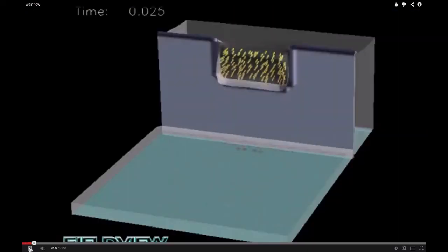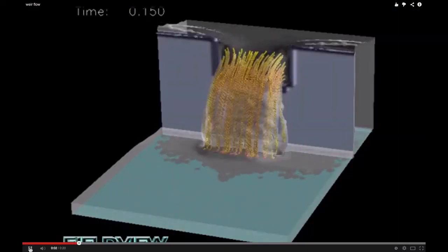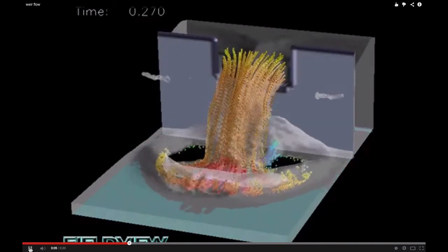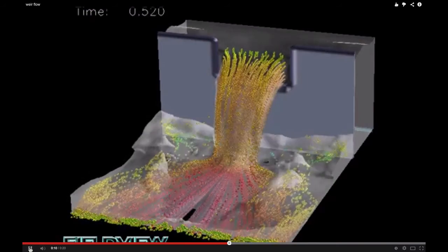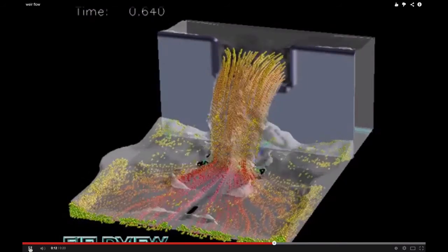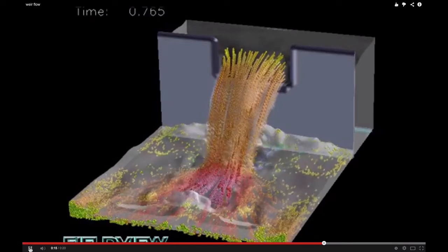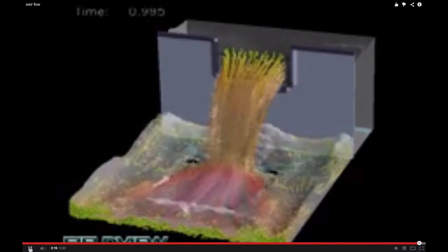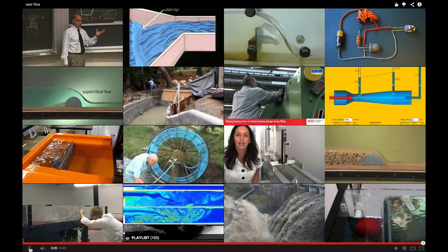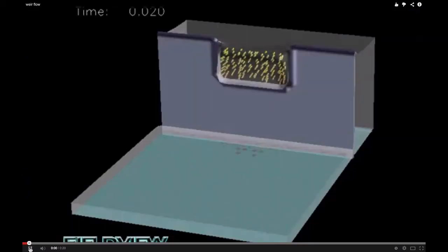And so those are methods which actually provide some kind of metering, but typically more commonly in use are methods that would use Bernoulli's equation in some way to measure flow rates, in other words, the V term in the Bernoulli equation, by one of two ways. The other two available terms are either fluid pressure or elevation. And so in different applications, you'd use either fluid pressure, as in the Venturi flume, in a pipe to measure flow rates, or you'd put a weir across a stream and measure the height of the stream above that weir and be able to use that as an indication, if you like, of the water flow in the system.